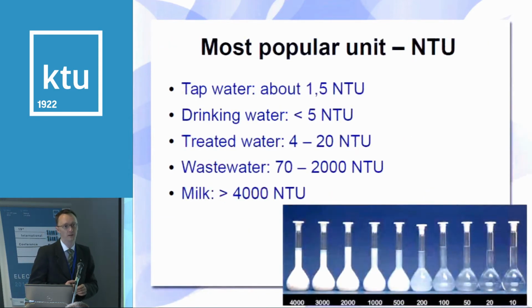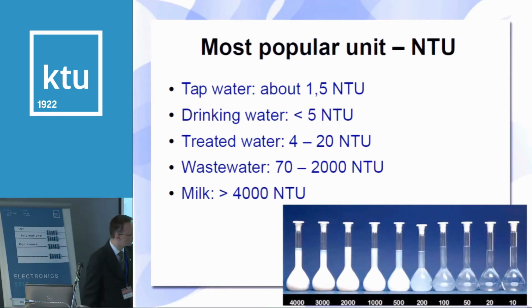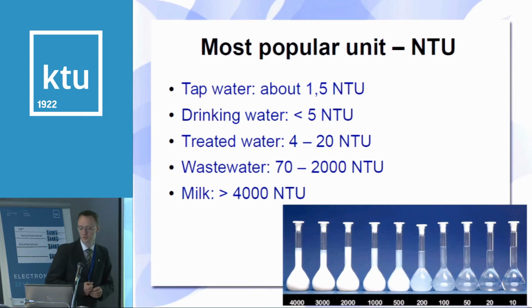Turbidity is measured in nephelometric turbidity units, NTU. I work in the range from about 800 to close to 0 NTU, so from pretty opaque to completely translucent deionized water, which is the range of the waters you can expect in the natural environment.